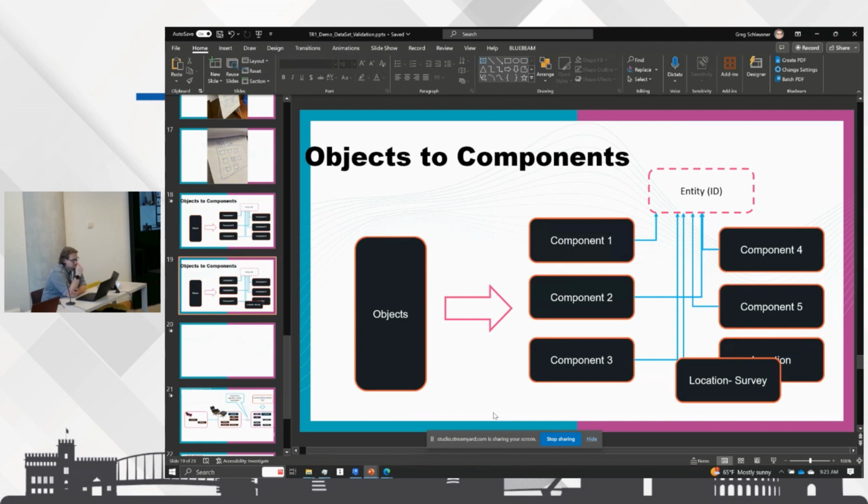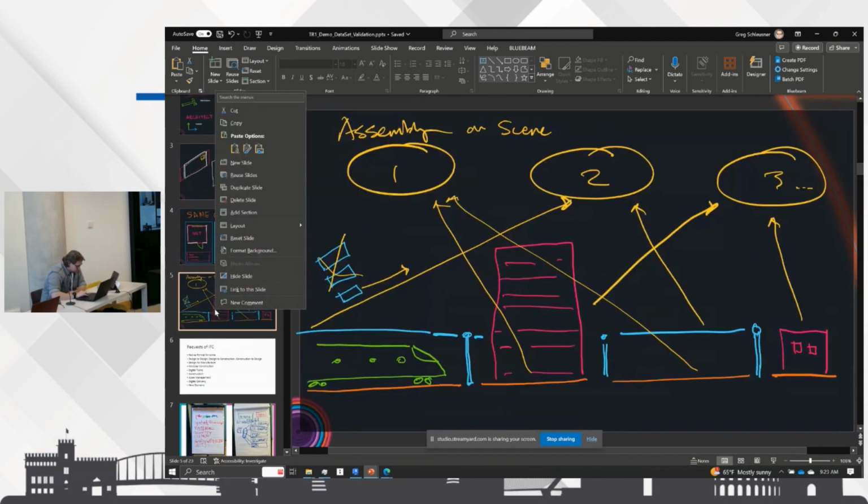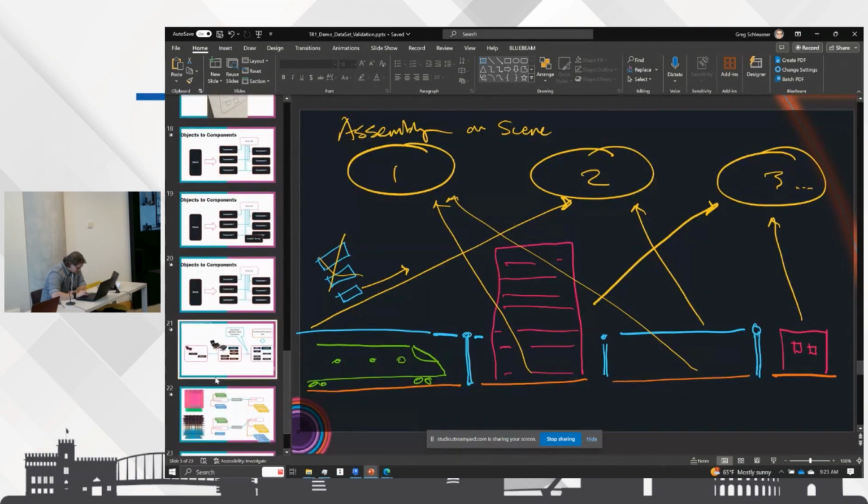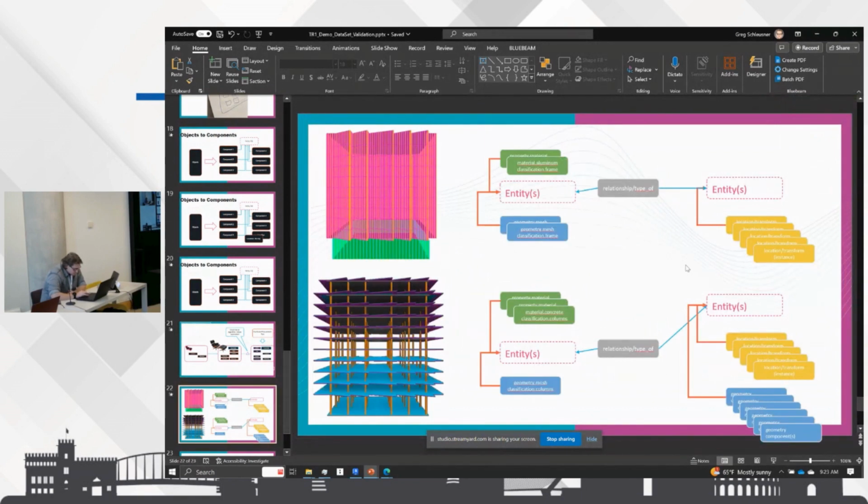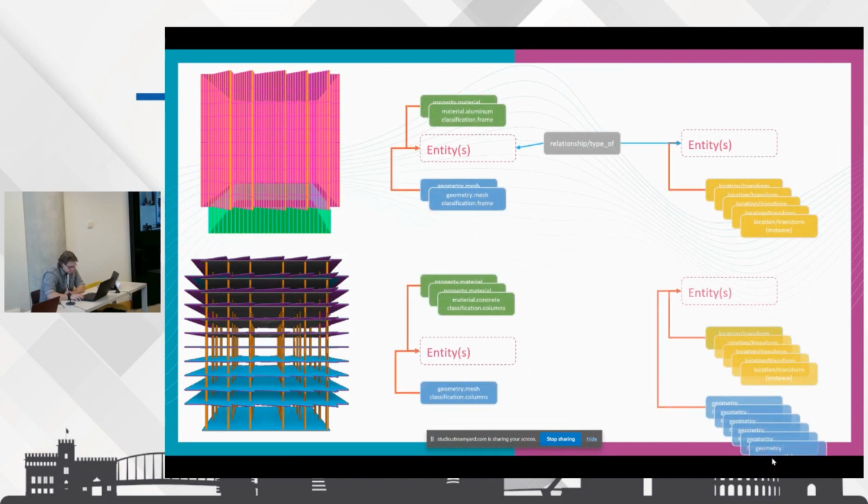So we have a mast that has specific width and depth, but the height is like 50 values that are possible. And in Revit language, we create one type, but we have instantiation of the height. So we are flexible. It's like a balance between how many files in the folder you have versus how many folders you have. And I think there is a need for flexibility in that topic because even different companies will always decide a bit differently depending on how they use the library.